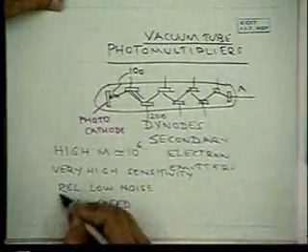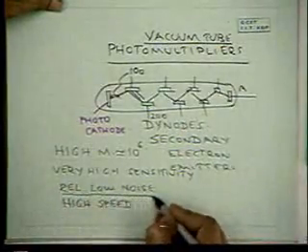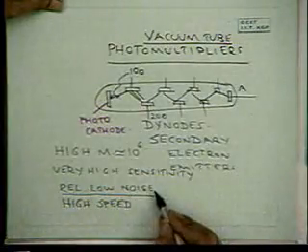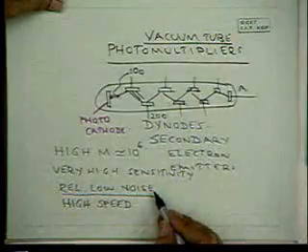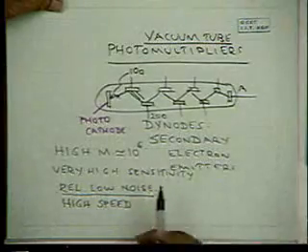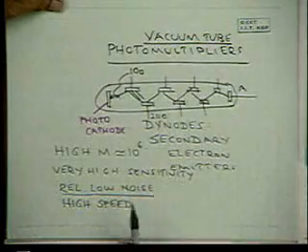However, we'll see that the noise of APDs is higher than the noise of photomultipliers, because of course the random nature of the emission process, and also in the case of APDs we have multiplication of both electrons and holes. Okay, so there's more randomness, and as a result the noise is not as good as photomultipliers.